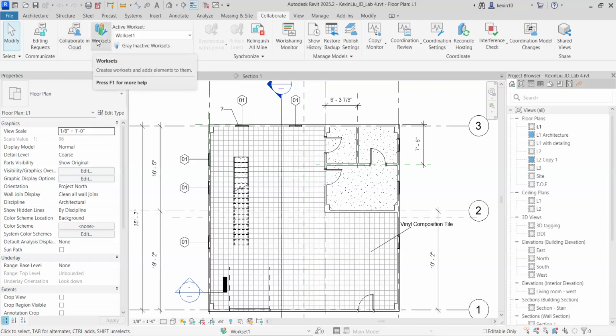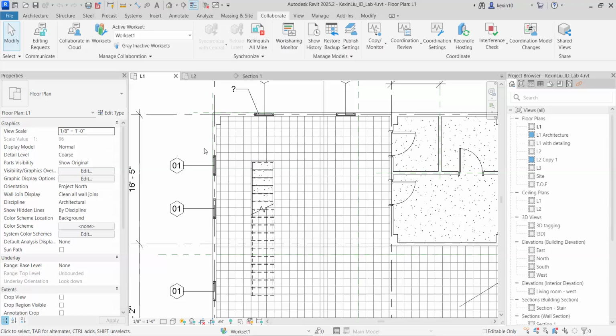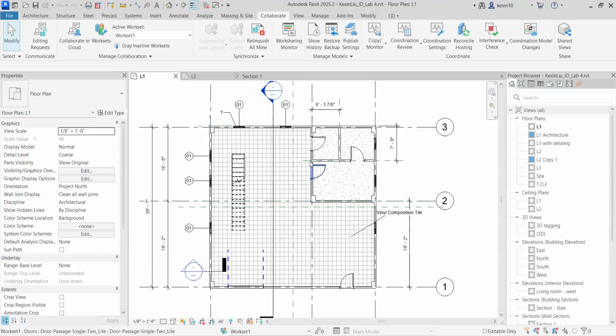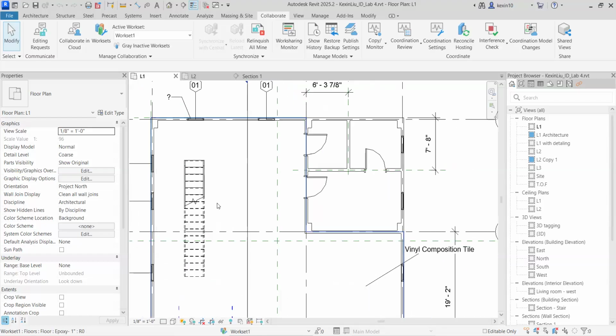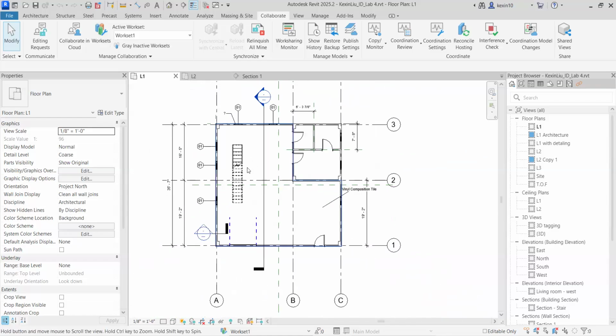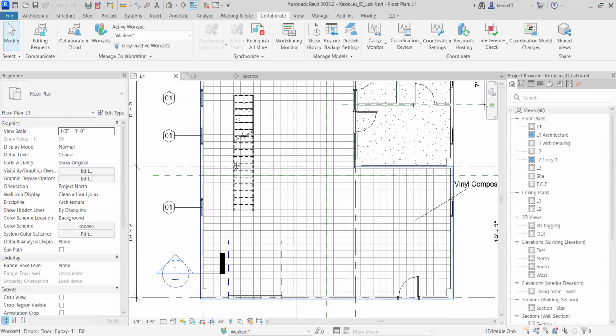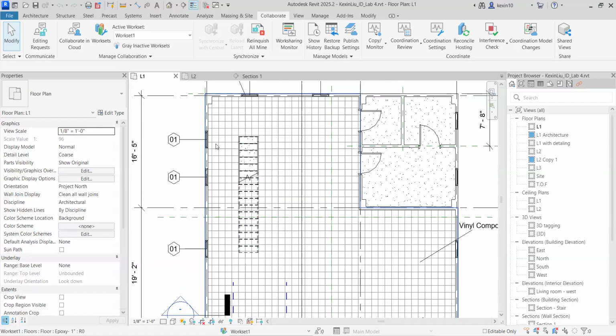And also you can see the work sets. So you can see the definition, create work set and assign elements to them. Only the assigned users can add the elements in a particular work set. So for example, if you have specific elements like walls, you want to dig a hole in your walls to do some pipelines, but you don't want other people to mess up your other elements like your stairs or your floors. So you can only assign the walls in your work set.